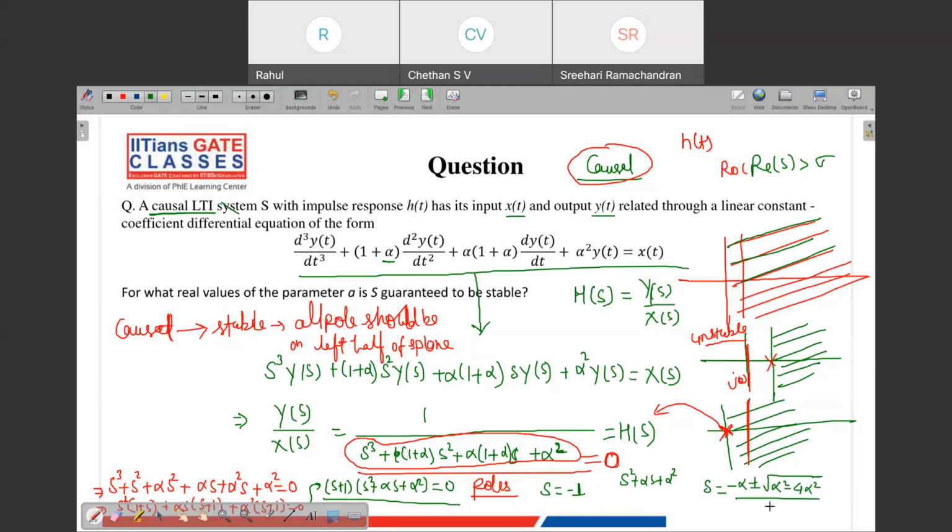Okay, by 2. Now in this expression, this term will give you the imaginary part, right? Because you see this is alpha square minus 4 alpha square. When you take out the alpha, you'll get under root -3, which is the imaginary part. And only this is the real part. And generally the real part is going to decide whether it is going to fall on the left half of S-plane or the right half of S-plane.